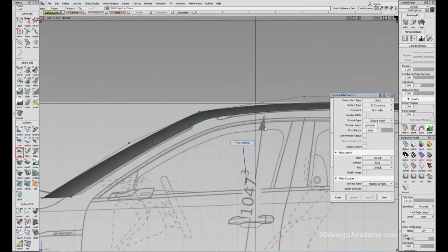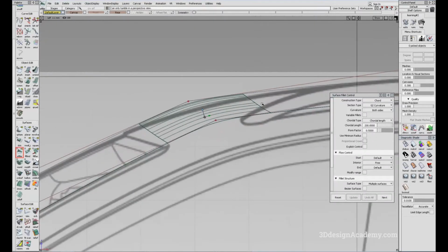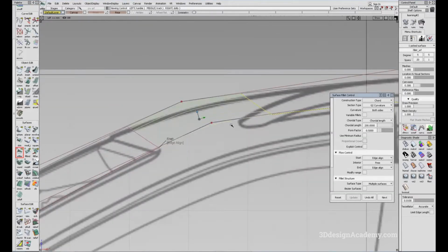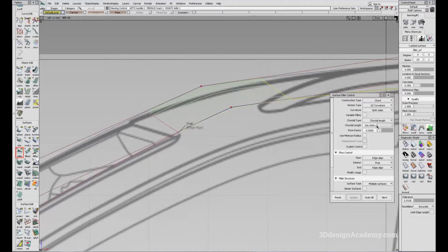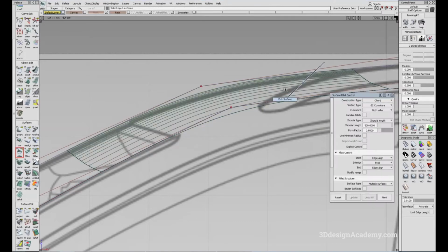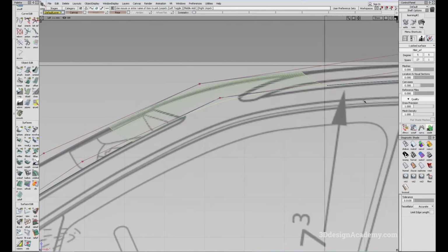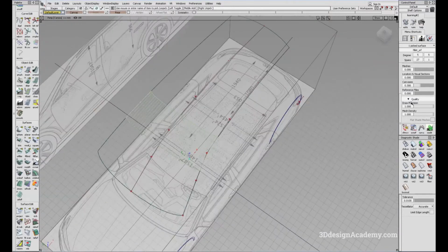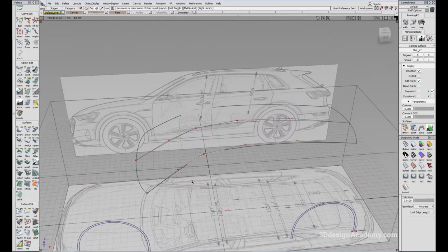It looks like we need to make it a lot bigger, because the curve on this fillet needs to mimic this profile on the canvas. So let's make it big. Let's start with 500 and see how that looks. Right now it's kind of hard to see because of all the lines, so I'm going to turn the lines off by turning the isoparm off.